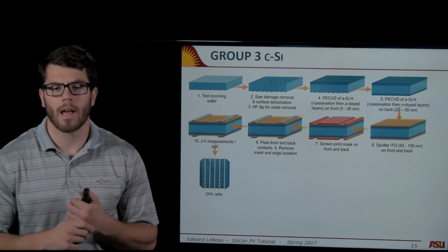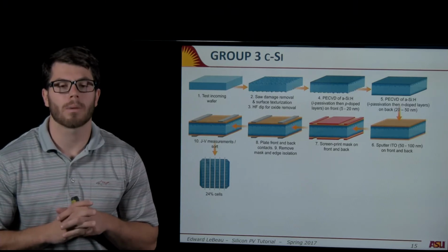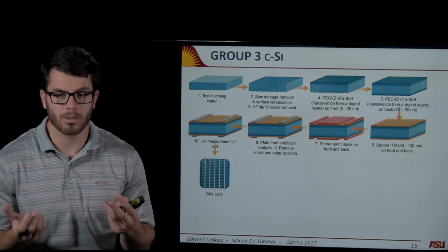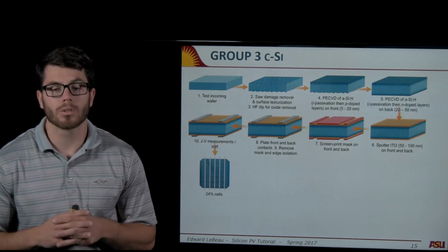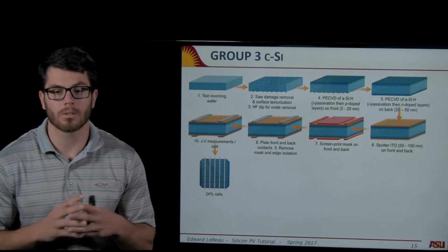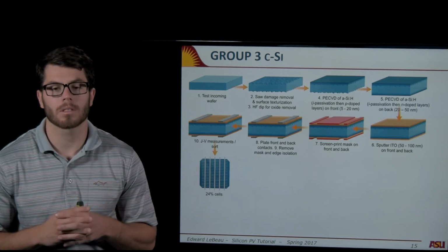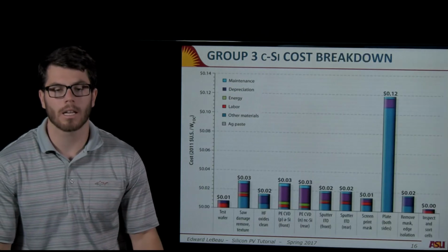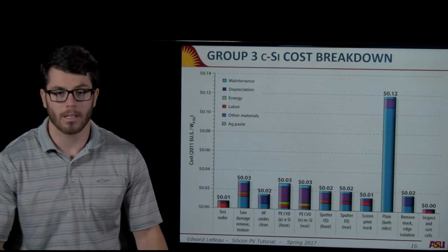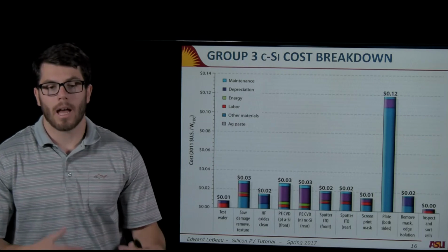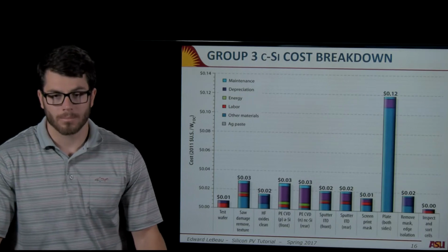And then in addition to adding that amorphous silicon layer, there's a thing called a TCO on the front, a transparent conductive oxide. That transparent conductive oxide is indium tin oxide. And that reduces your series resistance and reduces the shading because you need less fingers. Again, this increases the amount of steps and our costs. But let's see what the breakdown is like. Well, again, materials, depreciation, but all the more materials on this, right, from that indium tin oxide. And that adds up to about 31 cents a watt. So again, that went up a little bit more on the wafer level.